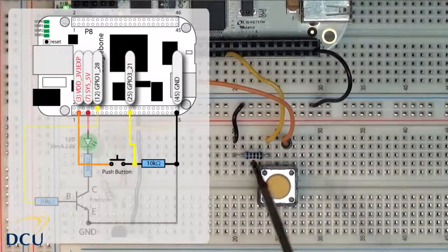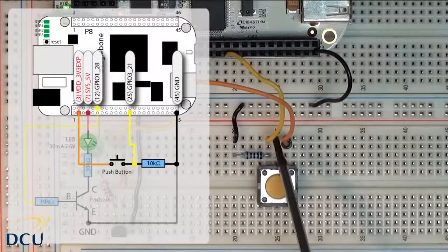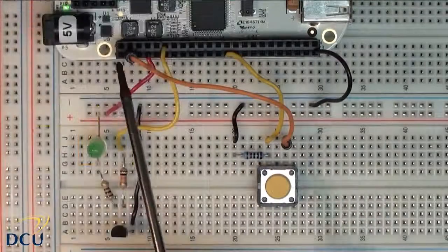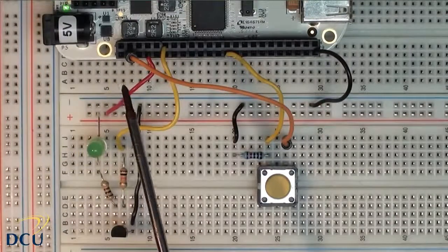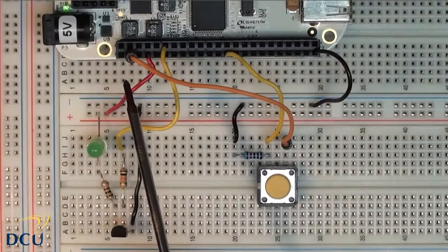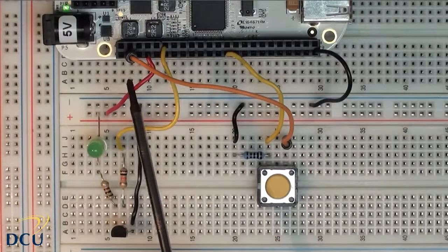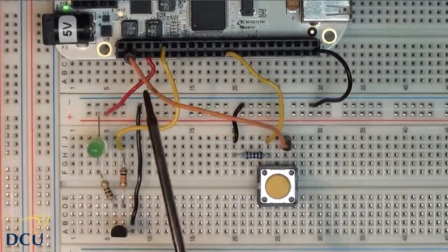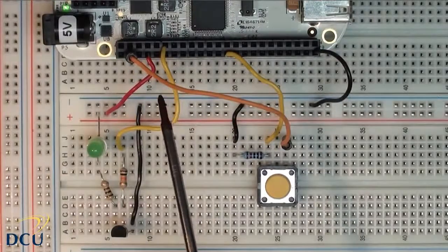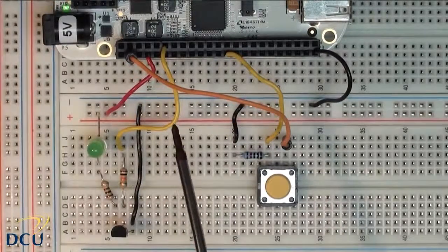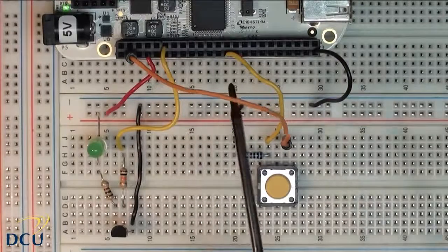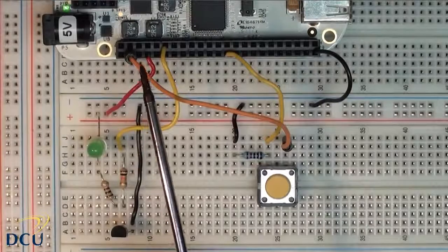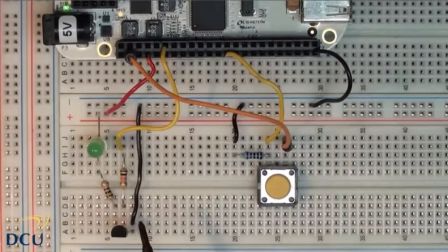So when you close the button, it means that we're causing this pin to go high. Now very importantly, this orange wire is connected into pin 3 of my Beaglebone, which is VDD 3V3EXP. This is a 3.3 volt supply. We would damage the board if you were to connect this to 5 volts, as the GPIOs have an upper limit at 3.3 volts. So just be careful that if you have got a high line that you're driving it from the 3.3 volt supply.